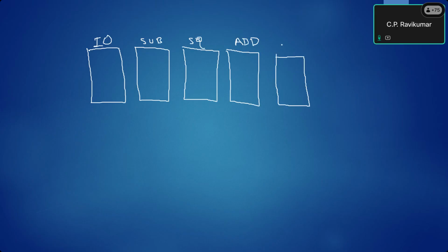This is an asynchronous design, man. There is no clock here. So add and then square root. This is based on a handshake protocol. Each of them may individually need a clock. See, the subtractor, you may want to use a clock, or the square rooter, you may use a clock, etc. Right? But between the two of them, they don't have a clock. Okay, these are all independent modules. They are not clocked together by the same clock. Right?